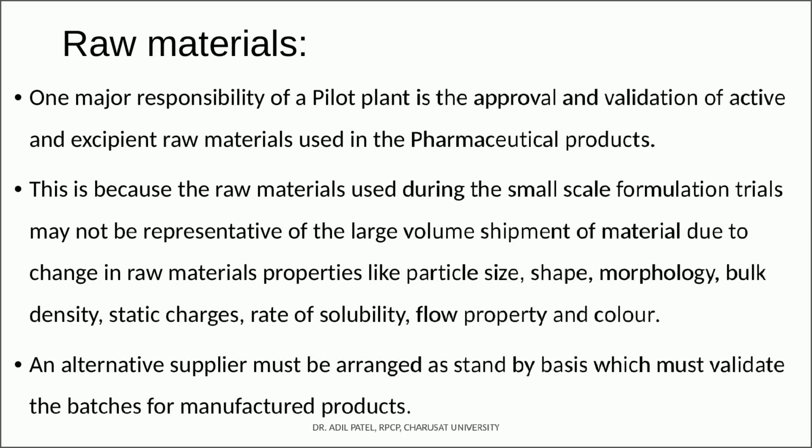Last would be the raw material, right? In the lab we are working with a small quantity of ingredient. At the pilot plant and at a large scale manufacturing facility we are working with a huge quantity of raw material. Because of this difference in quantity, there are many issues which arise which are completely absent at the lab scale. So you have to be very careful and very specific with the handling of raw material. One major responsibility of a pilot plant is the approval and validation of active and excipient raw material used in pharmaceutical products.